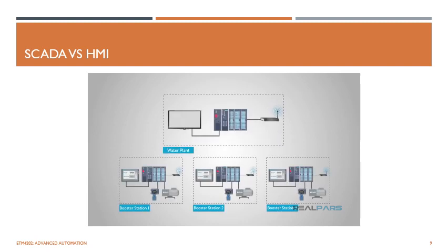So what did we learn today? Hopefully, you now know the difference between a SCADA and HMI. They are different but can be used together to create a very functional and useful industrial tool. A SCADA system is comprised of remote systems all tied together at one central hub. Our example was the water treatment pumps that were located all over a water district. They were able to be controlled and monitored from a central location at the water plant.